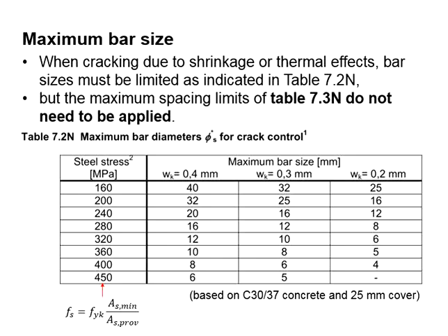For a typical high-yield steel bar, we will provide 10 mm bar diameter. This will be the smallest bar size used for the slab in general practice. Most likely this will not be assessed in slab design. Even if it is assessed, there is very high chance that the maximum bar size will not be exceeded.